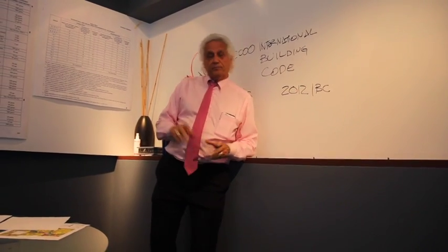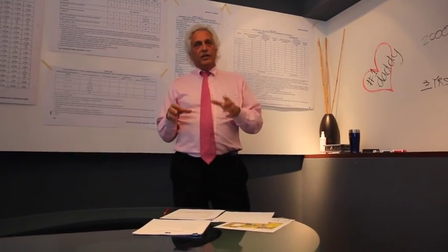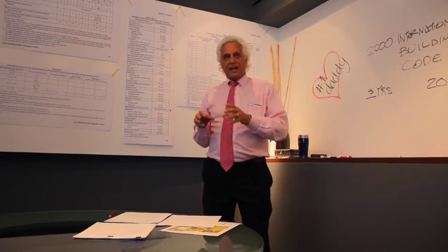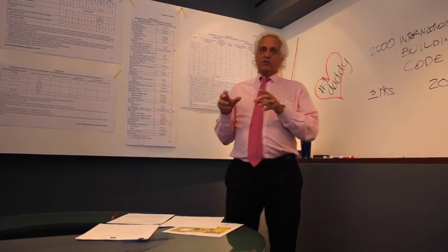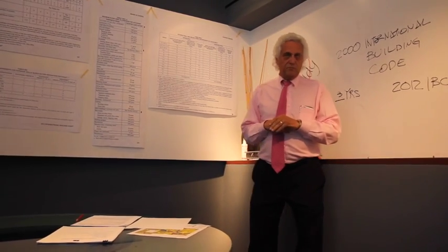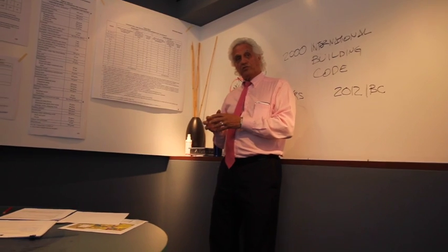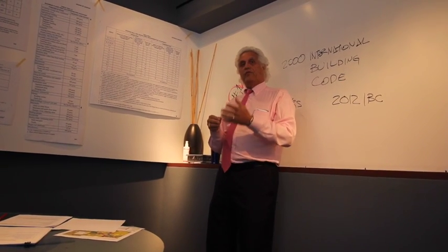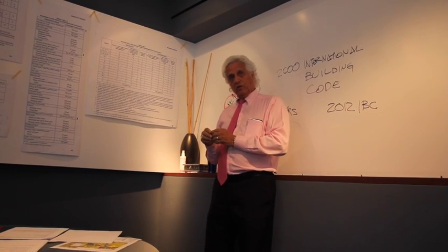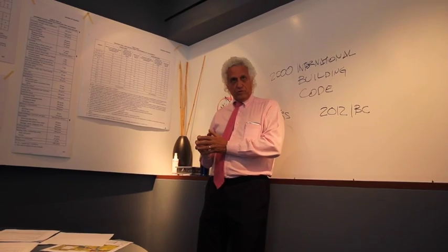So it worked. The thing that you need to remember is that the American with Disabilities Act is federal civil rights legislation. It is not a building code. Therefore, it's only enforceable in the courts. If there's an issue with accessibility in a building and you want to get in compliance with the ADA, you have to file a lawsuit in federal court, and then the court will decide the merits of the case, not the building official. Barrier-free design is a Michigan law, and that's the building official's area of responsibility.